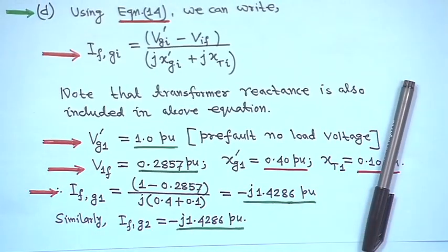So, in this case, for the 3-phase fault, we have taken some critical things, and particularly the Z bus building algorithm. Step by step you have to formulate, and a couple of examples have been shown to you on how to compute the fault voltages and the line fault currents. We have also shown how to go for the Z bus building algorithm. You just have to move step by step, but a lot of computation is involved.